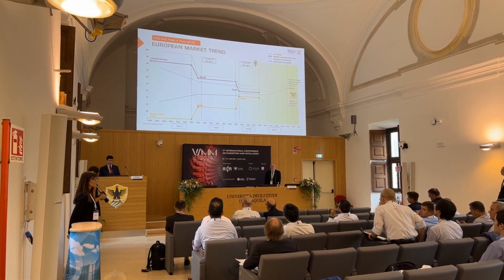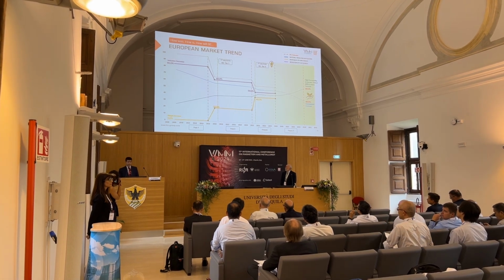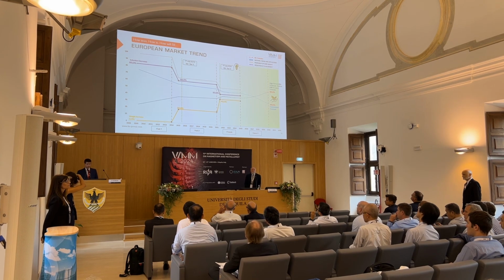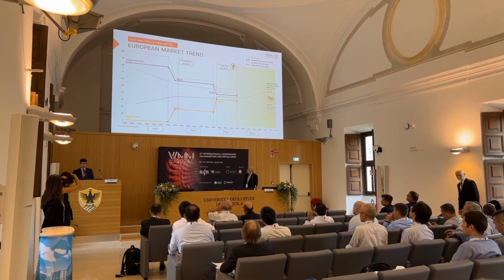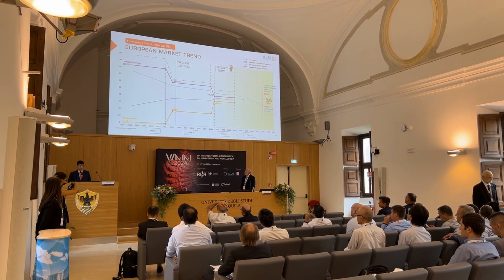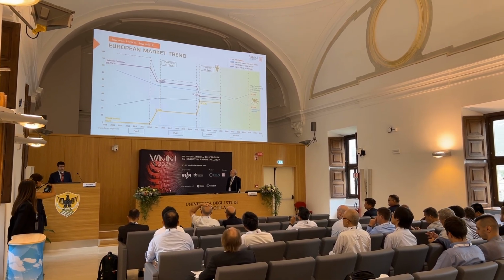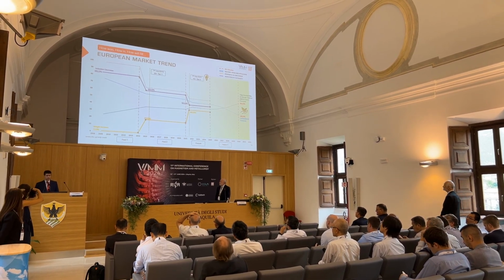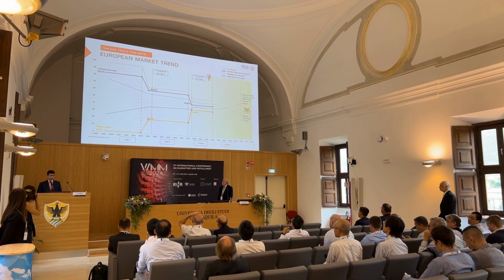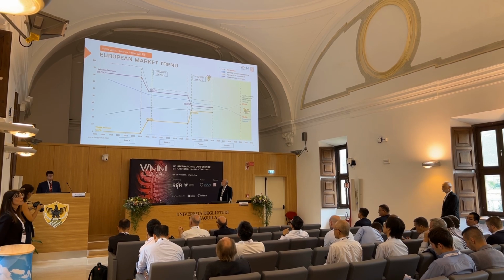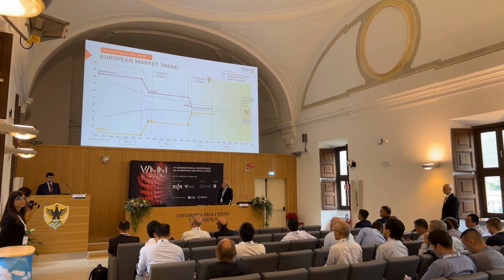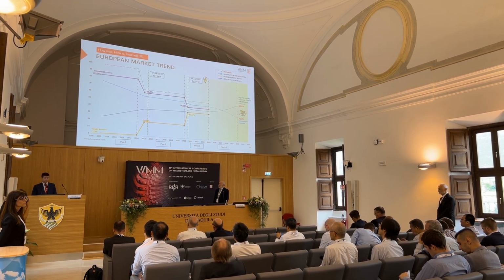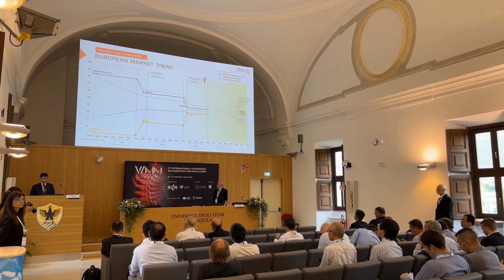Yeah, that's a very interesting question. In Europe, a Tier 3 regulation is not yet defined, but everyone is looking for new steps of this regulation. The idea, of course, is to reduce the losses again, but also take into account the green source of the material. From one side, of course, the idea will be to go to material with losses below 0.60 watt/kg, but at the same time we know how difficult it is to produce a low-loss material and make a big step in the developments.